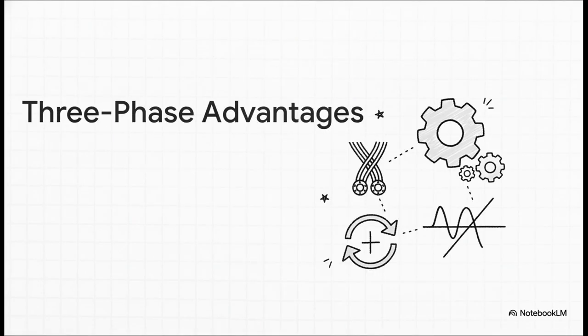So, let's lock this in. You probably came in knowing AC power exists, but now you know exactly why the grid is three-phase. It guarantees constant power delivery, which eliminates that destructive mechanical vibration. Economically, it requires smaller conductors, drastically reducing copper costs. Functionally, its fixed phase sequence drives motor rotation. And mathematically, that 120-degree shift defines the strict line-to-line voltage relationships that power our industries.